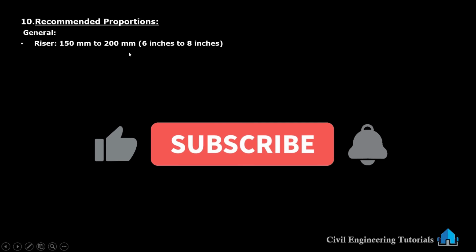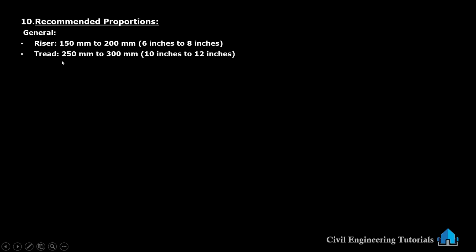Next, recommended proportions. So generally riser is 150 mm to 200 mm, that is 6 inches to 8 inches. And tread usually 250 millimeter to 300 millimeter, that is 10 inches to 12 inches.